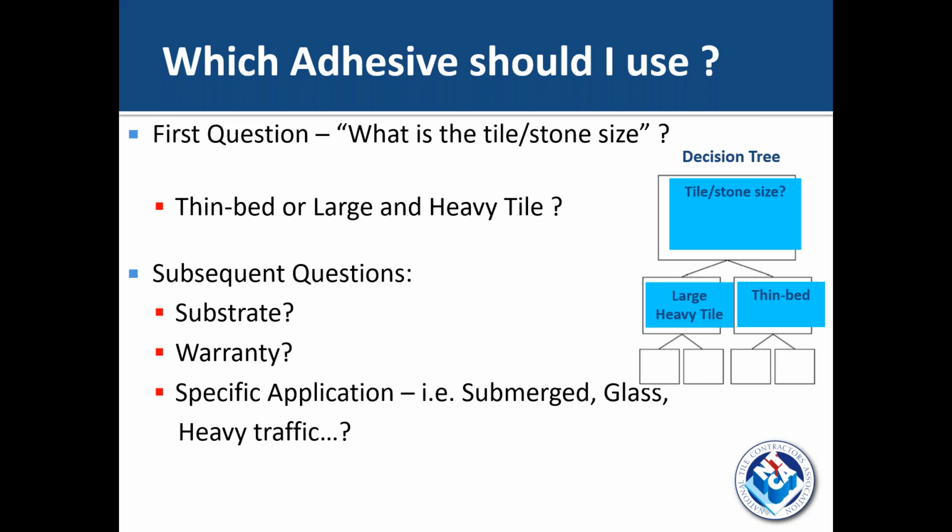Same person, how much creep can occur in adhesives? Oh my goodness gracious. I think, with movement joints, you want to achieve the appropriate coverage, which would be 95% for wet or exterior and 80% for interior. Right, that's the most important. And then the right specified gap for the movement joint.